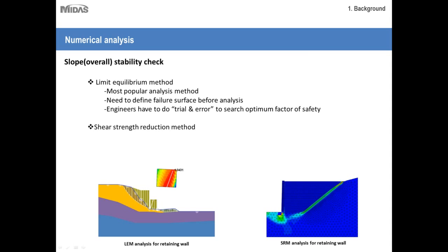And as it proceeds with lowering the shear strength value, it hits a point where the entire slope is mobilized, and at that point it clearly shows that the maximum deformation would occur at this particular layer at this particular force, and therefore you can easily assess when the failure will occur and what will be the failure plane.